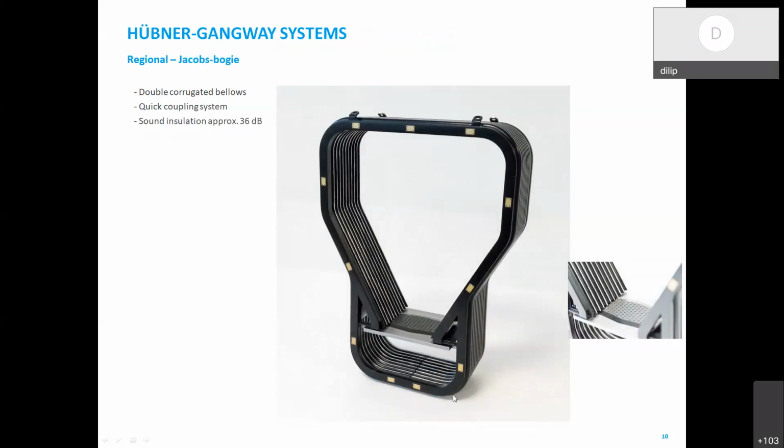In this particular arrangement, you are seeing a bridge arrangement. This is called a combination bridge arrangement. These are the bellows, which will come between the end walls. And there is one more bellow below this plate. In between this recess, the mechanical coupler will be passing. Here the coupler will also be concealed. This type of arrangement is used basically in fixed type train sets. The coupler will also be concealed in this, so that there will be no chance of any dust entry.